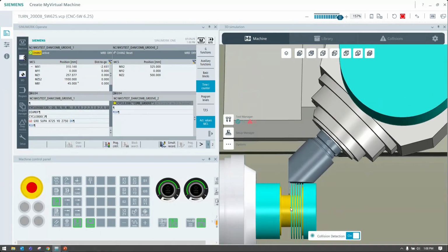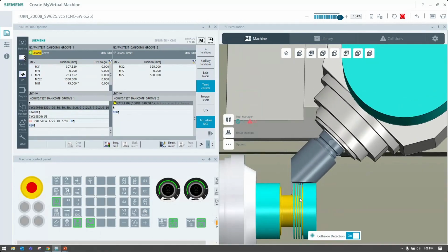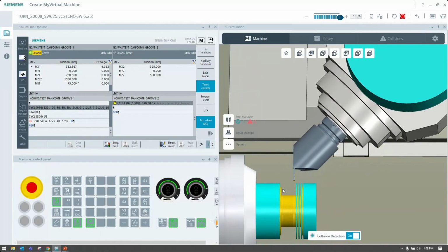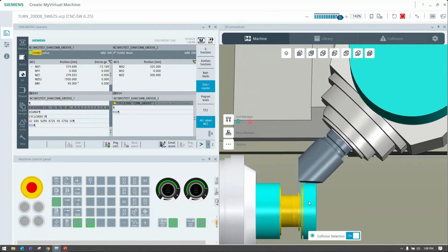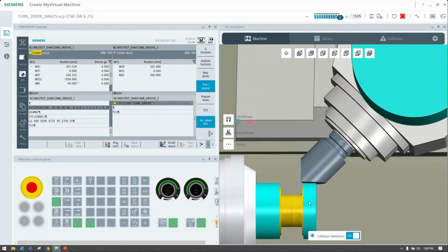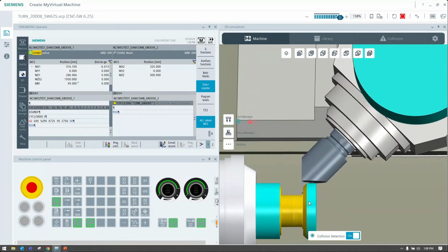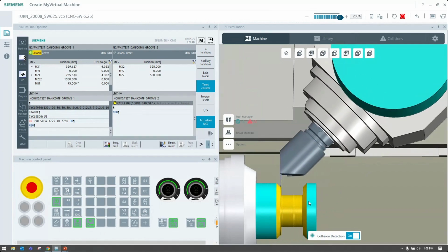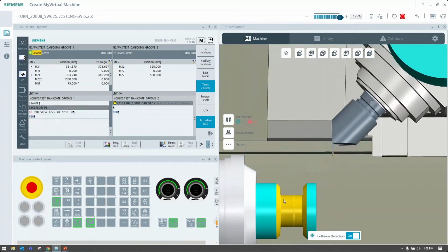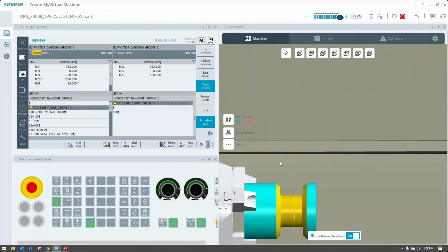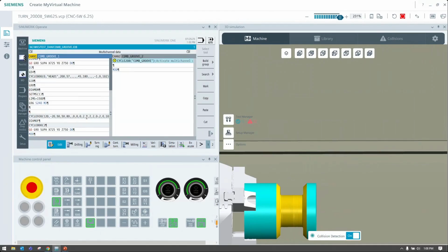If we look at the cycle time, just in this cycle we're at a minute. If we use the alternate, we're like a minute 20. So if you had not this virtual type of material, but steel or something like that, you might be 5 minutes for alternate, and you might knock it down to 4 minutes. So having this capability to really rough out a groove really helps out.